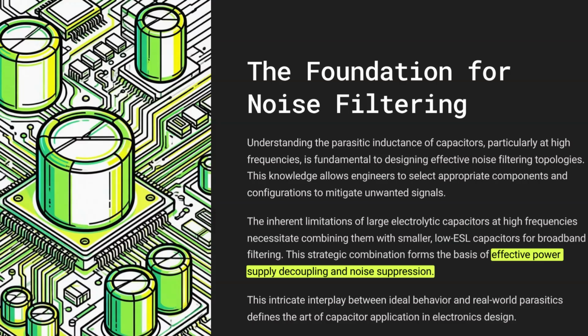It's the essential compromise. And, while we're on it, we should mention tolerances. Resistors can be very precise, 1%, 5%. Capacitors are much worse. 20% is common, and 10% is considered pretty good. You have to design for that wide variation.